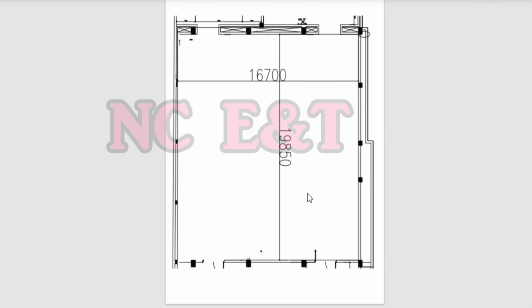As per NFPA, for the calculation of the actual distance between the sprinklers and between the sprinkler and the wall, there is one procedure. We select one remote area of size 1500 square feet, and we make the calculation for this remote area to calculate these dimensions.